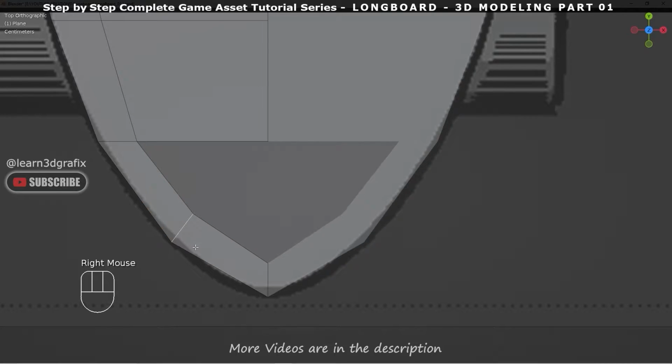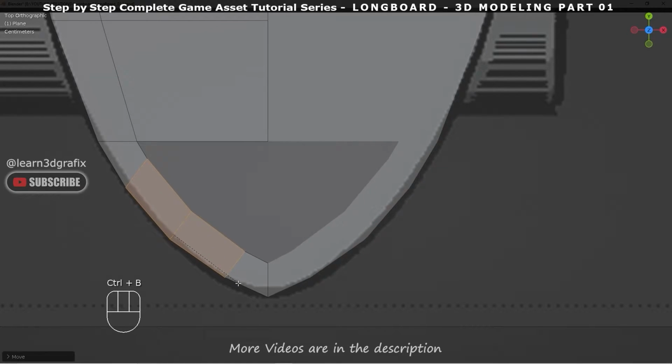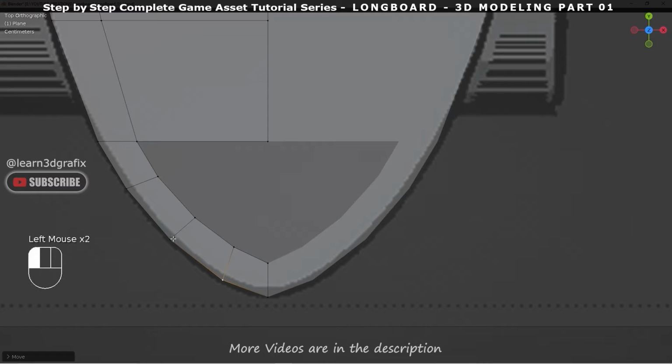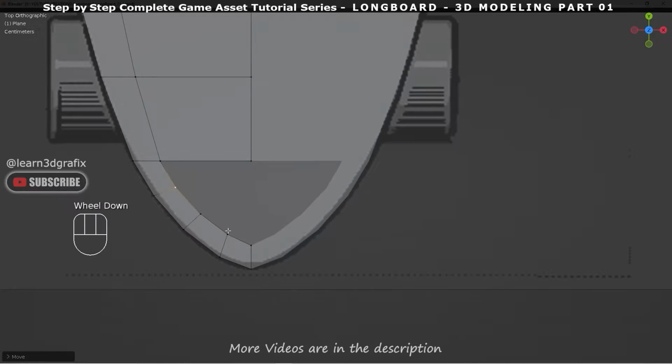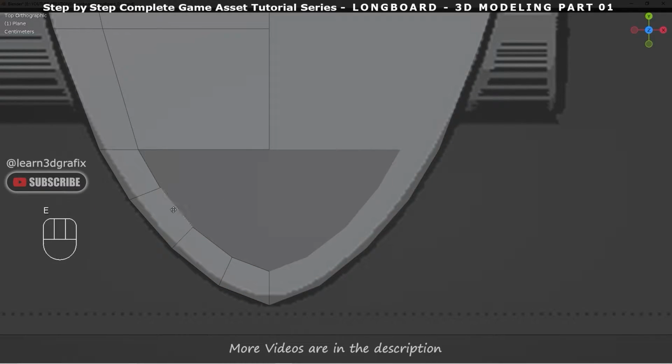Press Ctrl B to bevel the edge. Select this edge and extrude it and snap it to the middle.